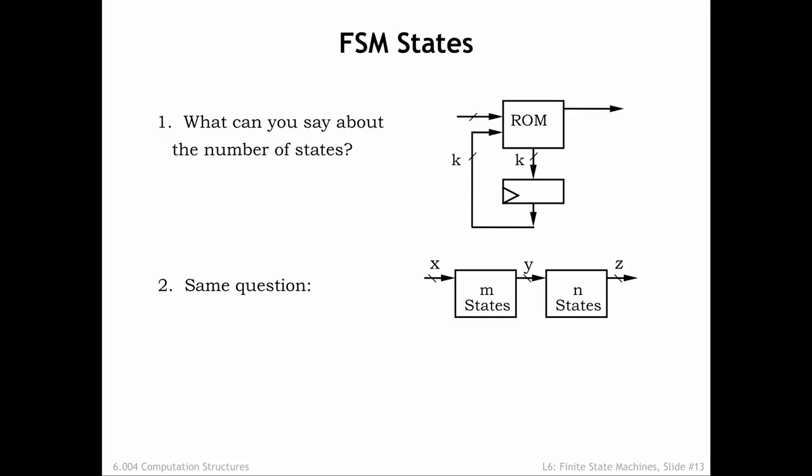Note that the answer doesn't depend on x or y, the number of input signals to each of the component FSMs. Wider inputs just mean that there are longer labels on the transitions in the state transition diagram, but doesn't tell us anything about the number of internal states.